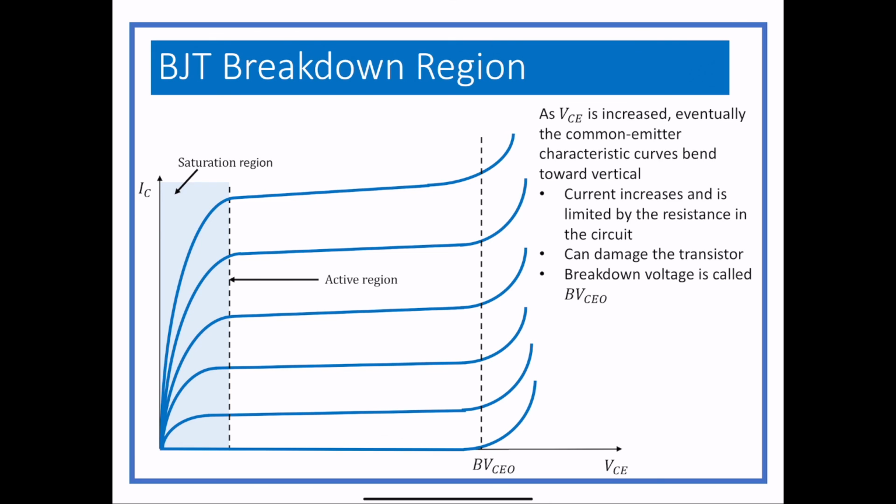We don't cover most of that here; that was the kind of thing we used to cover in Electronics 1 in ECET, all the ICBO and ICEO. We don't cover any of that in here, so you don't have to worry about it. That's the one reference to something being open. I'm not going to tell you how to find this value. It is listed on a spec sheet. Don't operate the transistor at a greater voltage than this. Don't set VCE to be bigger than what the transistor can handle.